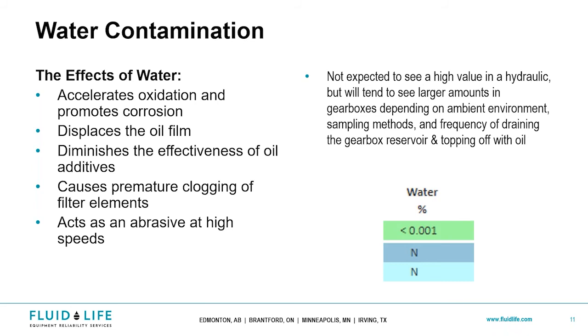So this can diminish not only the oil film or the effectiveness of lubrication itself, it could also diminish the effectiveness of the additives within. Like those detergents, those antioxidants, those extreme pressure, anti-wear additives, all that stuff can be affected.